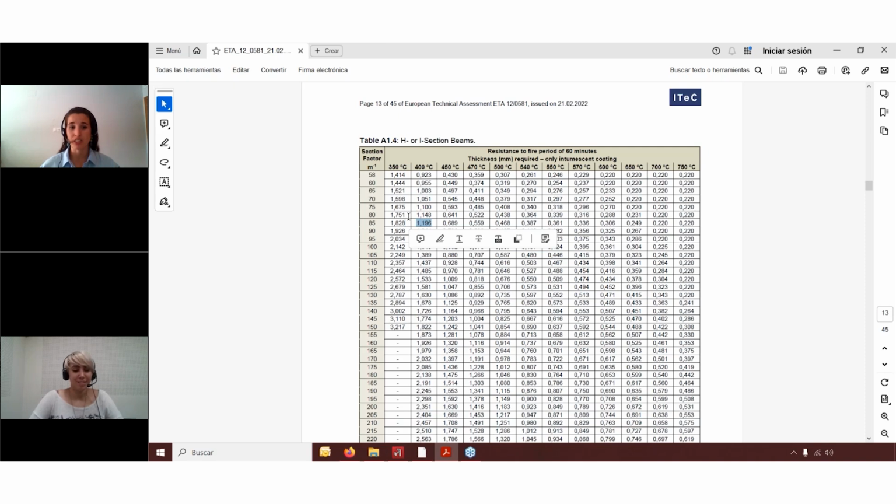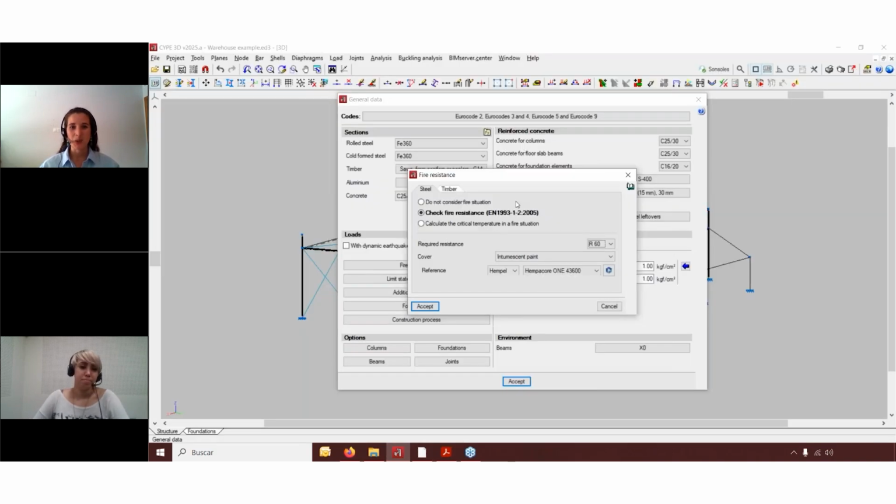So what's the difference between using at least the critical temperature and, of course, the help that is already giving you that thickness? It's that you save money. Basically, you are being very specific about which elements need what kind of coating, and that means saving money. So I think it's a good one. People love to save money.